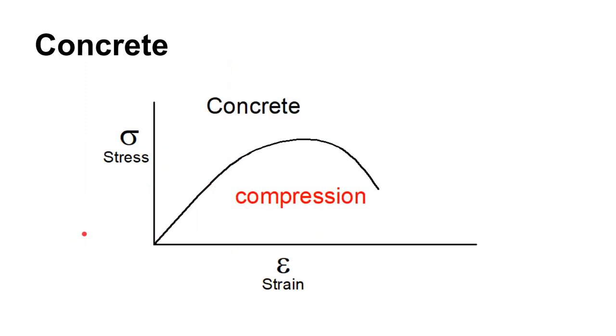Now, I included concrete here, but normally you don't talk about tensile testing concrete. Normally you do compression testing of concrete, and so you do get this little elastic region in concrete, and then as it begins to crush, it will form this kind of parabolic stress strain curve.